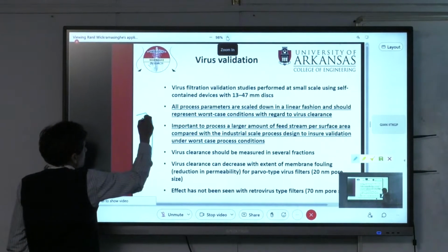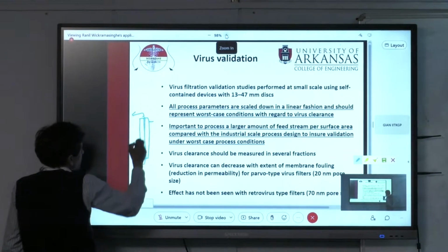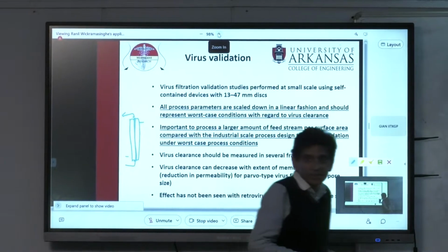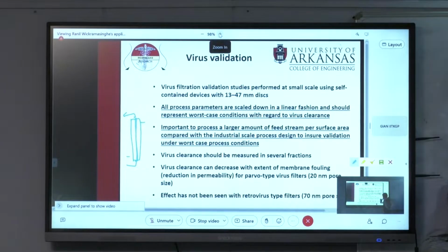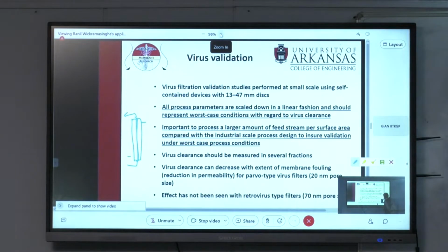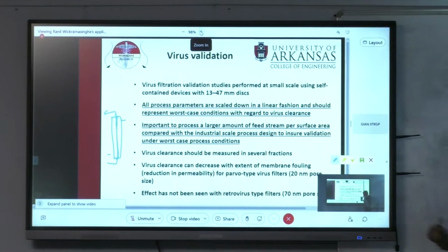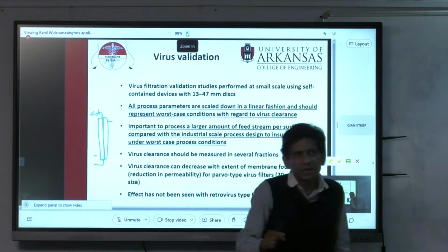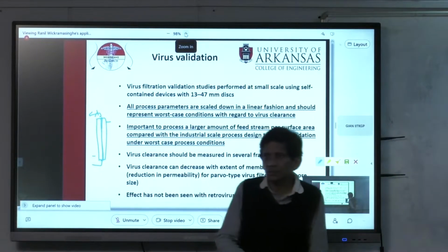So you have a feed port, a retentate port, and you actually have 2 permeate ports, but you run it with the permeate ports closed, okay? But you do have them, so they make them with the permeate port. That is sometimes useful when you're initially flushing and so forth, but they run in dead-end mode. Sorry, what am I saying? You run it with the retentate port closed, okay? So it's in dead-end mode, and one of these permeate ports is closed.